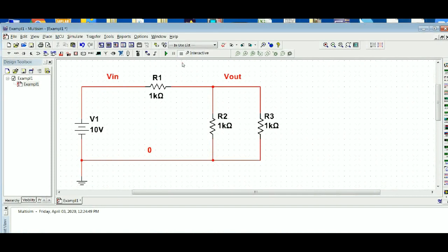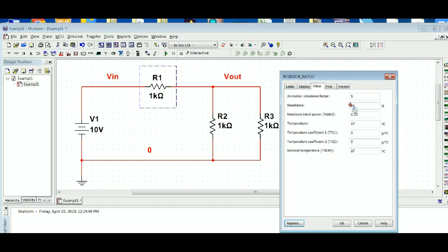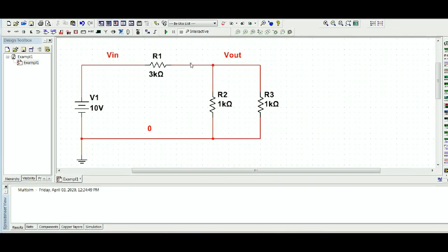So suppose that I want to change the value of this resistor to 3K. I'll click on the resistor, and there's the attribute, it's 1K. I'll just make that 3K. Notice that this is in ohms, so you have to put either 3000 in here, or you can use the prefixes, in this case 3K. Further, notice that the rating of this resistor is 1/4 watt. That means if I exceed this using a rated virtual part, I'll blow it up. Now, blowing it up in Multisim is a good thing compared to blowing it up in a real circuit if I forgot to calculate the power. Clicking OK now turns this into 3K.